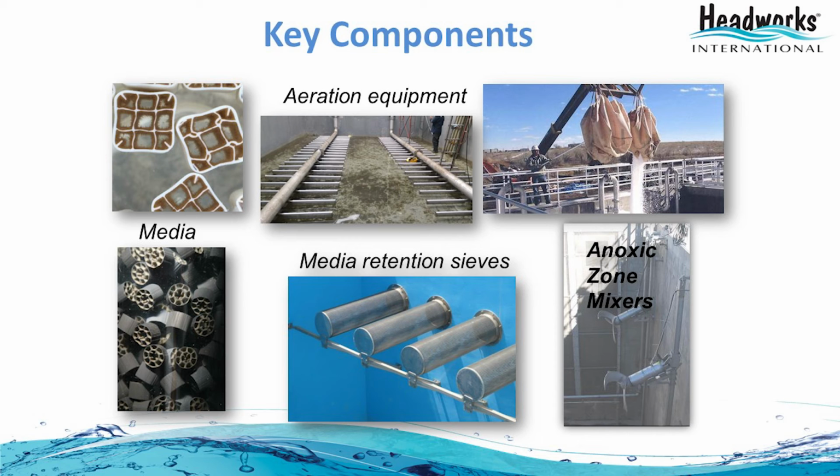In the case of anoxic reactors or anaerobic reactors, we use mechanical mixing. These are specifically made to work with the media in it, but we can also use the anoxic zone without media to save costs. These mixers are made of stainless steel. They have banana blade type mixers at slow RPM, and we have specific modeling programs to design them and position them within the reactor.